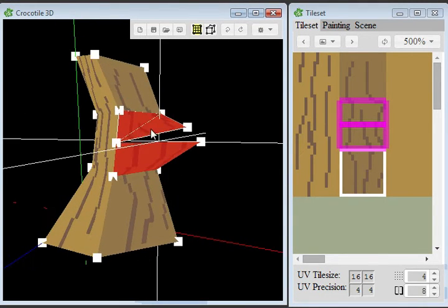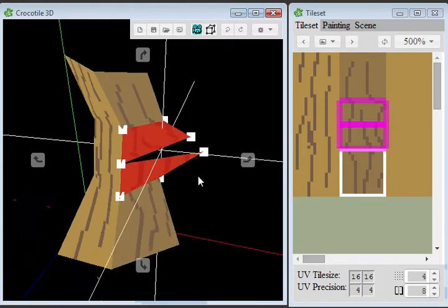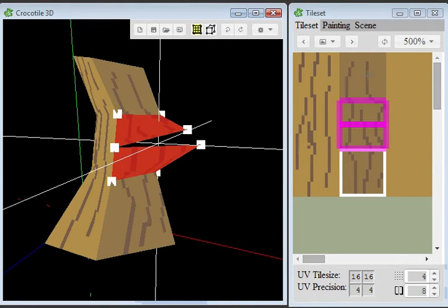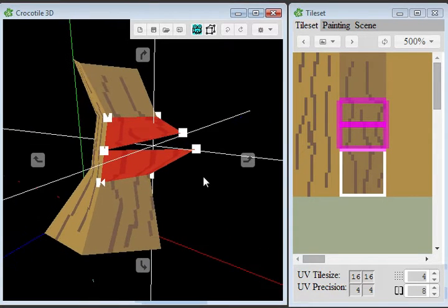So now as you can see, the UVs got split as well, so that might be good if you wanted to create a tile, then split it without having to create another tile and adjust UVs. Thing is, you can't combine tiles together. You have to undo it if you want to undo the changes.